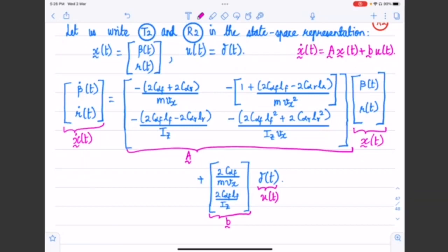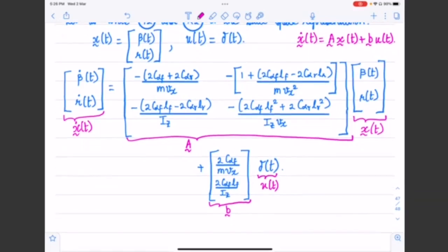Okay. As we know, when we studied the state space representation also, for the stability of a system, we need the eigenvalues of the state matrix to be in the left half of the complex plane, right? So that is a condition that we require. So consequently, we want to analyze this system for its stability by looking at the eigenvalues of the state matrix.